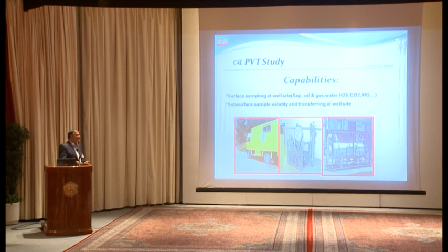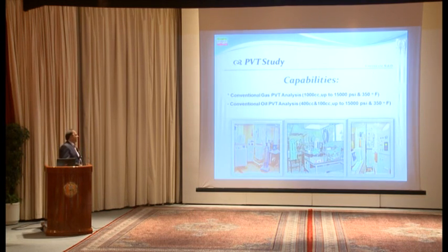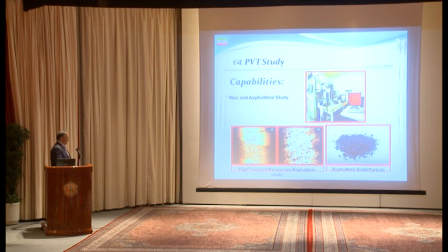The name of my presentation was about routine and special core analysis and PVT. Besides core study, we have all equipment related to conventional oil and gas fluid properties in RIPI, and also we have special systems. You see here the different generations of equipment in RIPI, from old to new generation of PVT systems. This system is for wax and asphaltene study by laser beam, determination of the onset of asphaltene and also the amount of asphaltene and wax.